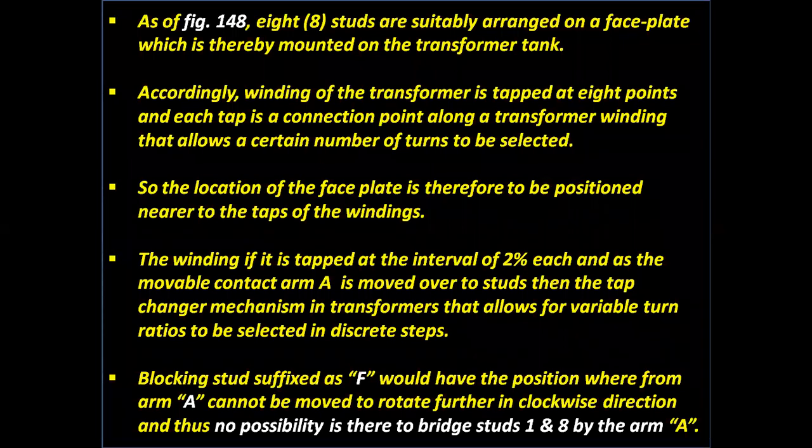As of figure 148, 8 studs are suitably arranged on a faceplate which is mounted on the transformer tank. Accordingly, the winding of the transformer is tapped at 8 points, and each tap is a connection point along a transformer winding that allows a certain number of turns to be selected.